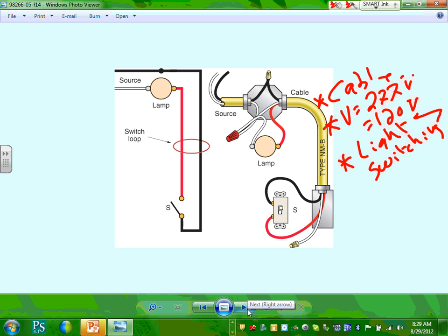What's the idea behind it? Because people can get rid of this switch and put a dimmer here, not a dimmer, a motion detector. Anybody install a motion detector? You bring the hot and you bring a neutral. You bring hot, switched hot, and the switch loop, and you have to bring a neutral for the electronics, to energize the sensing mechanism in the occupancy sensor.